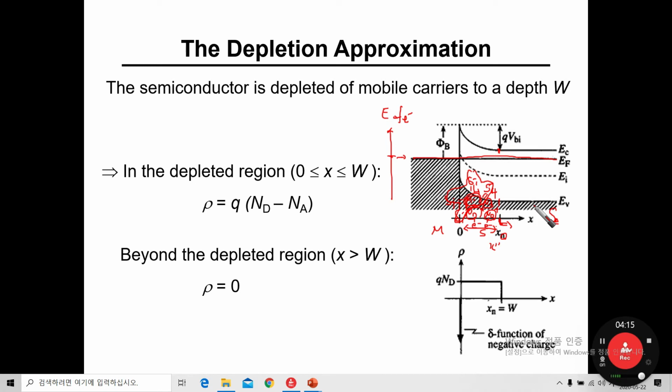Electrically activated means a certain silicon atom has been replaced with the donor, and it is well bonded with the four neighboring silicon atoms. The donor atom, coming from column 5 in the periodic table, has a total of 5 outermost electrons. 4 out of 5 electrons are used to complete the covalent bonds with the four neighboring silicon atoms. However, the extra one is left.